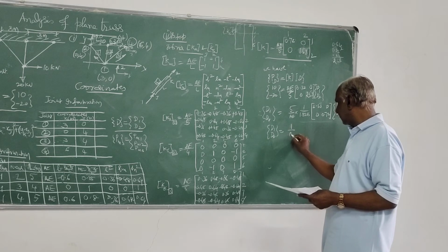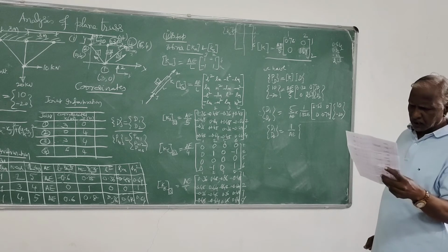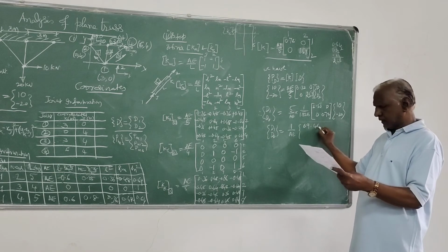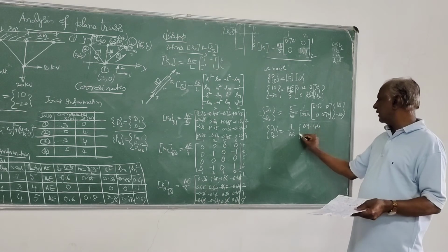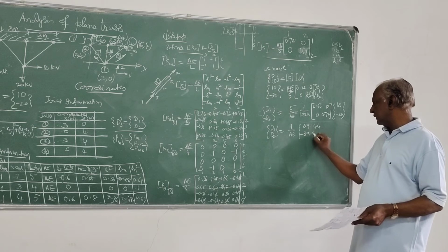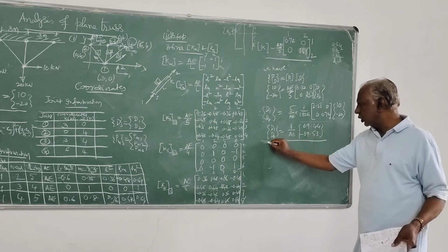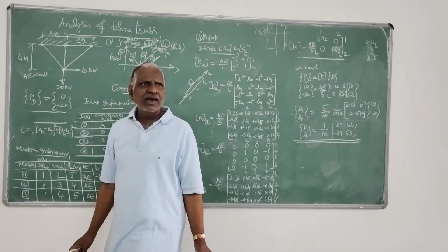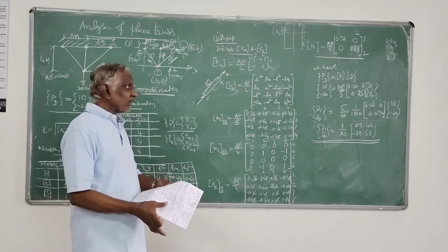If you simplify, I have determined the unknown displacements D1, D2. So 1 over AE, if you simplify, I will get 69.44 here, and minus 39.53 here. You can check this once. So this is my unknown joint displacement. One part of analysis is over. That's the first part of analysis, that's what I was telling.